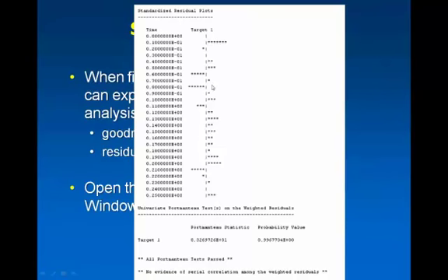It sort of shows you this tree where you can see which side of the simulation the residual data point lands on. So these are a distribution of your residuals, and you can see that some fall on the left and some fall on the right. If you had systematically everything on one side, that would show you that while numerically your objective function met your requirements, you're probably not a good simulation because you'd be systematically under or over predicting your values.